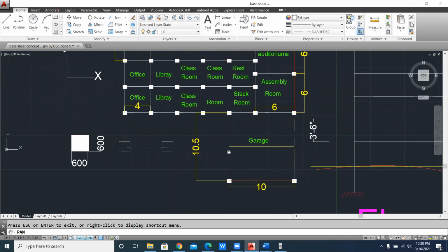And this one is 24. Okay, why do we normally provide the secondary beam? We normally provide the secondary beam in order to give support, because in the middle there is a large bending moment, due to the large panel, and we would otherwise have to increase the thickness of the slab.